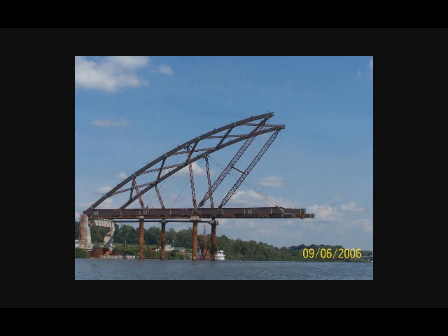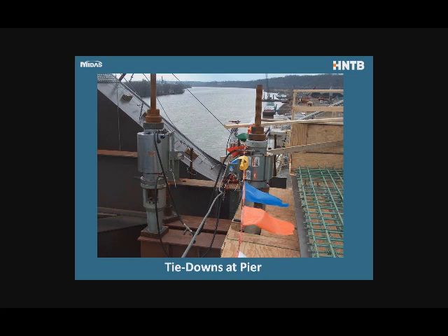This is an interesting stage because at this stage, if you try to estimate where the center of gravity of the arch is, it's actually outside of that front line of steel casing support. So the whole arch really wants to tip over, and you have to prevent it from uplift. You can see the uplift restraints. We are looking at the end of the arch.